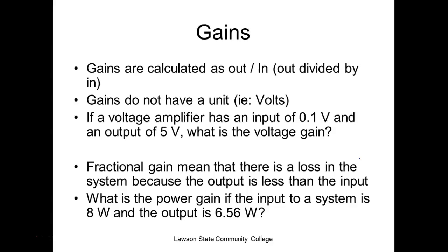If an amplifier, so what would be the voltage gain? Say I have an output of 5 volts and an input of 0.1 volts, or 100 millivolts. What would be the gain? Get out your calculator and let me know. I'm going to say 5 and divide it by 0.1. So what would my gain be? 50. 50 what?